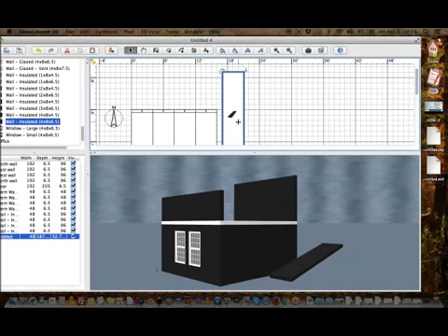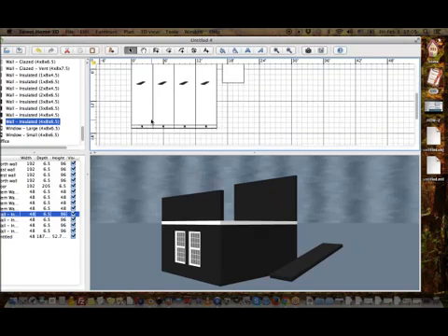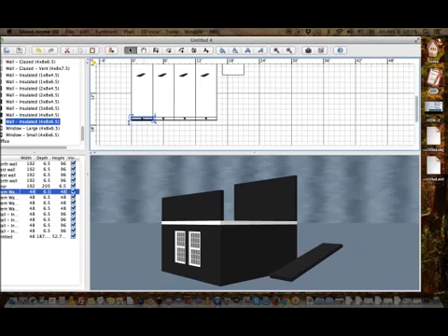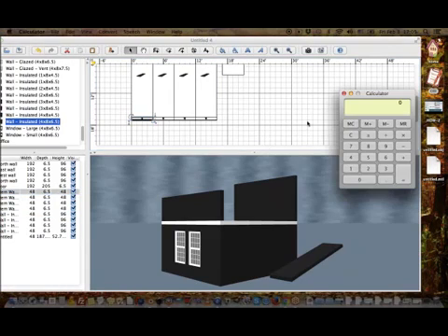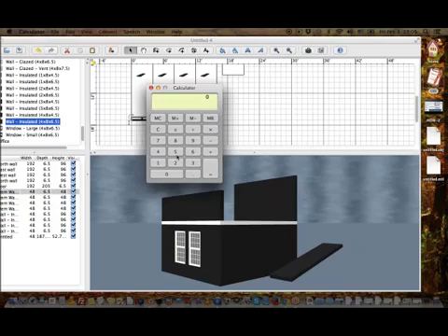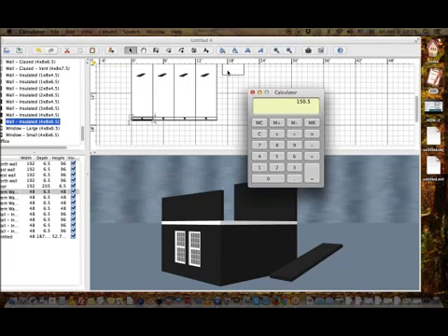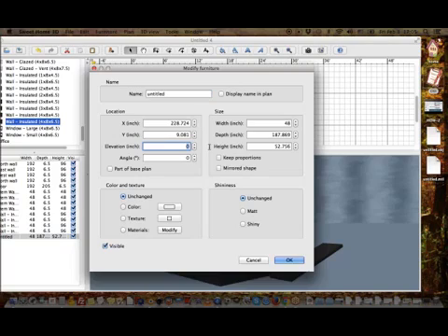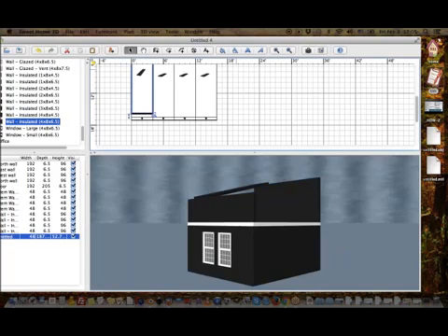Okay, so now I'm going to place this on top, and I've got to once again figure out what the height of my wall is. Now, the one I want right here is the lowest one. So I'm going to add up. I know that the bottom wall is 96, and then I have a floor that is 6.5, and then I have another 48 inches. So that tells me the height that I need to place this at, which is about 150.5, at 24 and at 96.